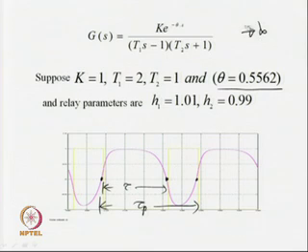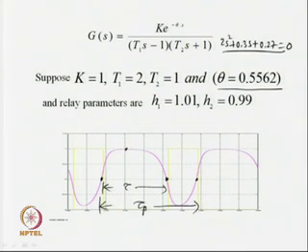As far as analysis of the system, like the previous case, it will yield a characteristic equation of the form 2s² + 0.3s + 0.27 = 0. How do you get this characteristic equation? Again, finding the peak amplitude, which is of magnitude 1 now, gives us the relay gain h = 4 × 1.01/(π × 1), which is approximately 4/π, about 1.27. After getting this as 1.27, you multiply it with the loop transfer function and get the characteristic equation.